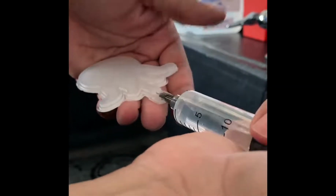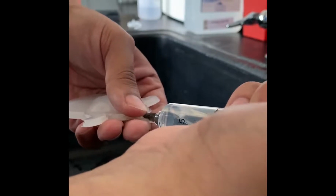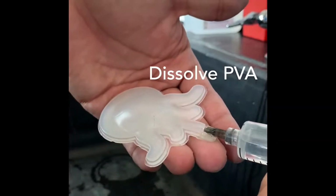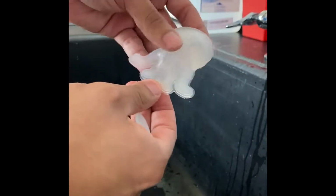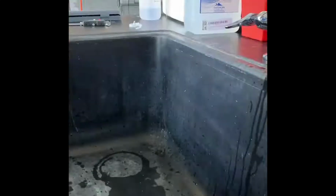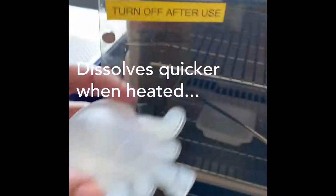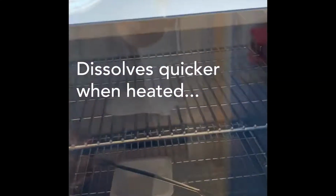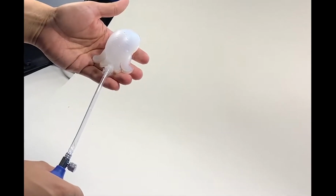Then remove the silicone bladder from the mold and proceed to inject it with water. This is in order to dissolve the PVA that is inside the bladder. It sometimes helps to move and agitate the mixture, but in the end we found that heating it actually helps dissolve the PVA much quicker. Once you're done, insert an air tube and inflate.